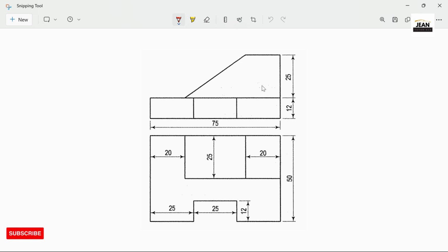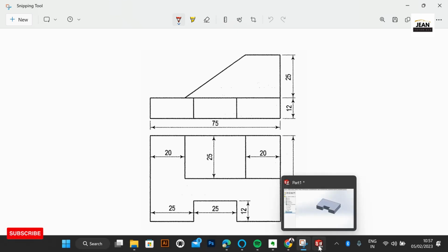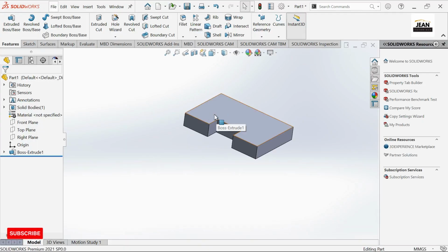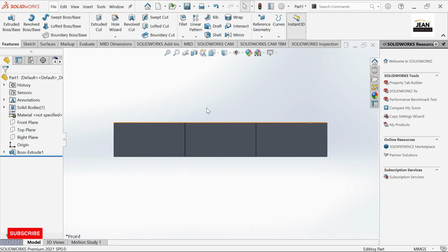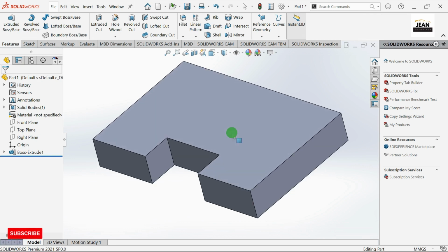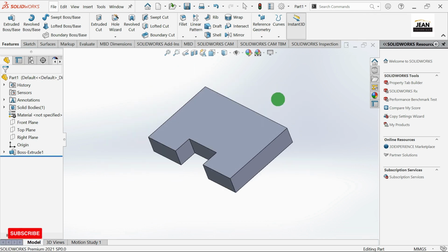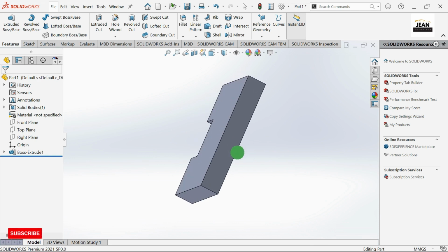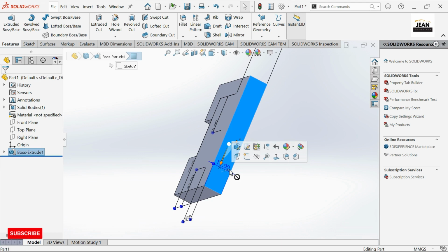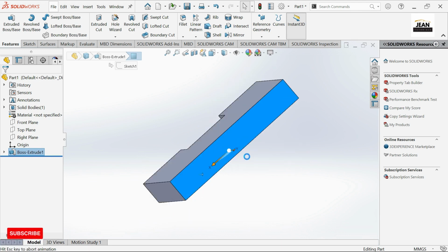Now it's time to choose a plane to draw on. So let's come on our design, which is this one. Here you see we have a front side, and in order to reach the back side, you can use your mouse, drag, and move your mouse. You can get this back side. So click on this line, it will be easy for you, and then activate sketch.